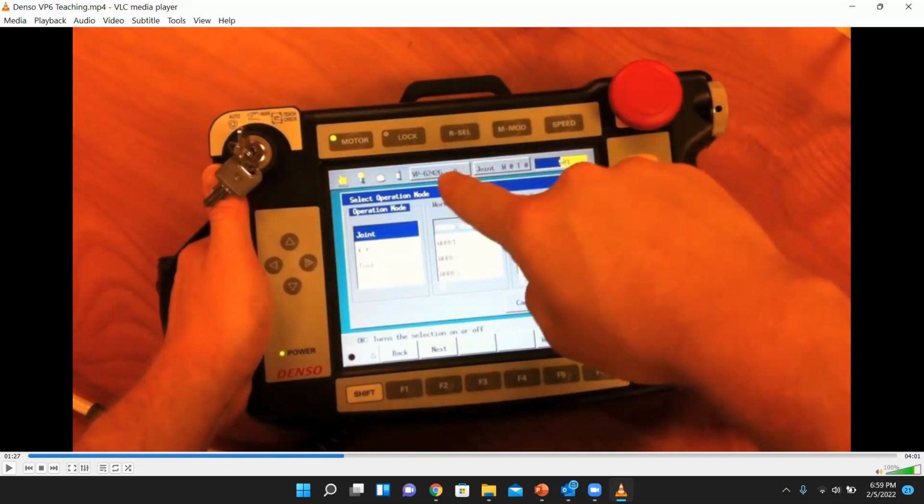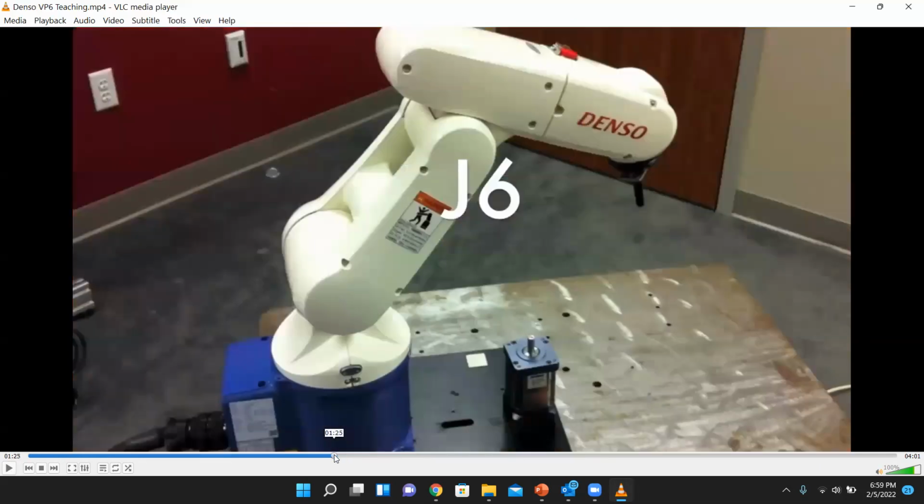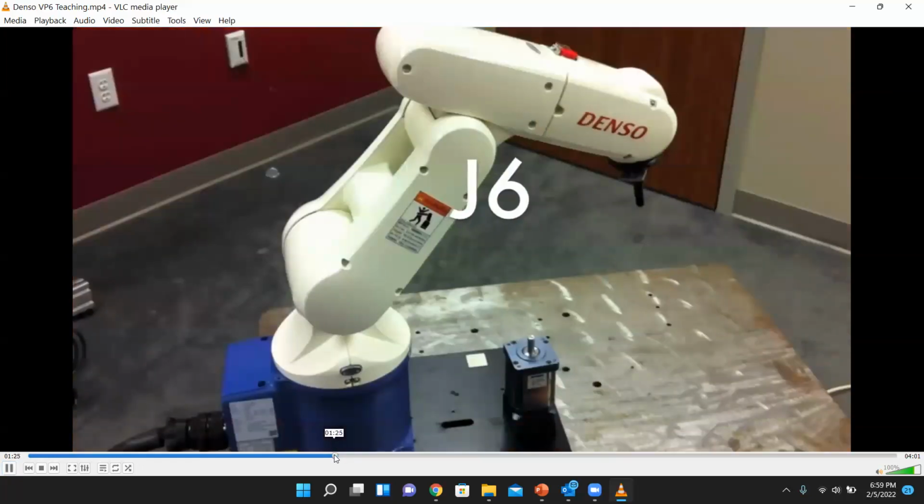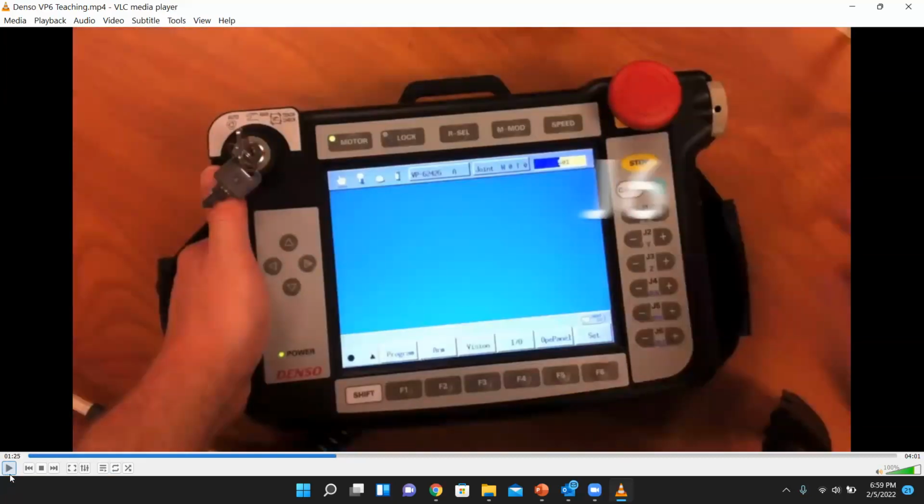Okay. So if you are operating with a, so let me pedal back and show it again. So look at this last joint rotation, this rotation, right? If we select the motor, this one, which is the rotary motor on the end effector, right? So that motion is not required if you do laser cutting, welding like that. Okay. And if you have a robot to write on the board, again, you don't need that rotation.